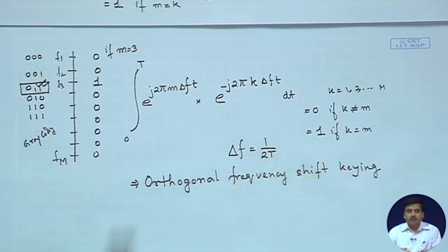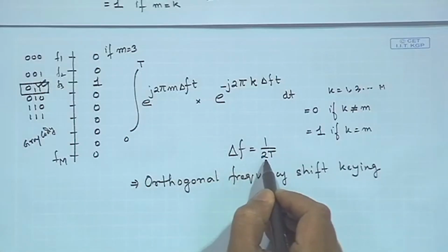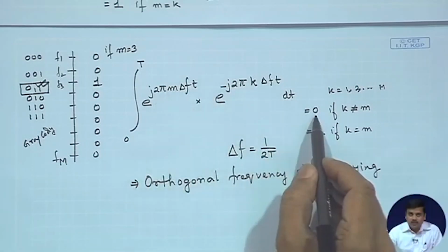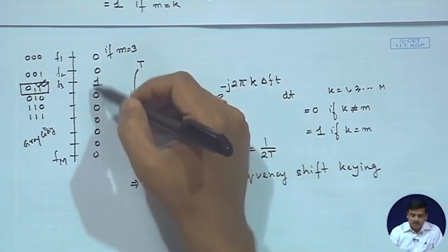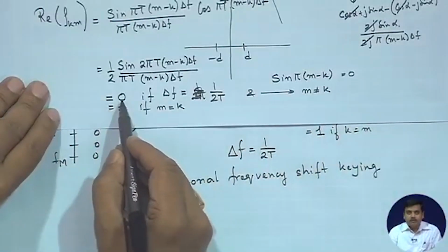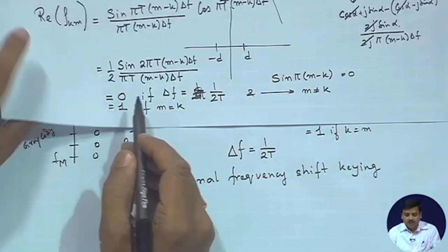this, you can always find out another set of orthogonal frequencies, but you will be using more bandwidth than needed. Whereas, if you make delta f smaller than this, then you would no longer be able to maintain this orthogonality, right. There will be interference amongst these signals, and you will not get a correlation which is 0, you will get some values of correlation, right.